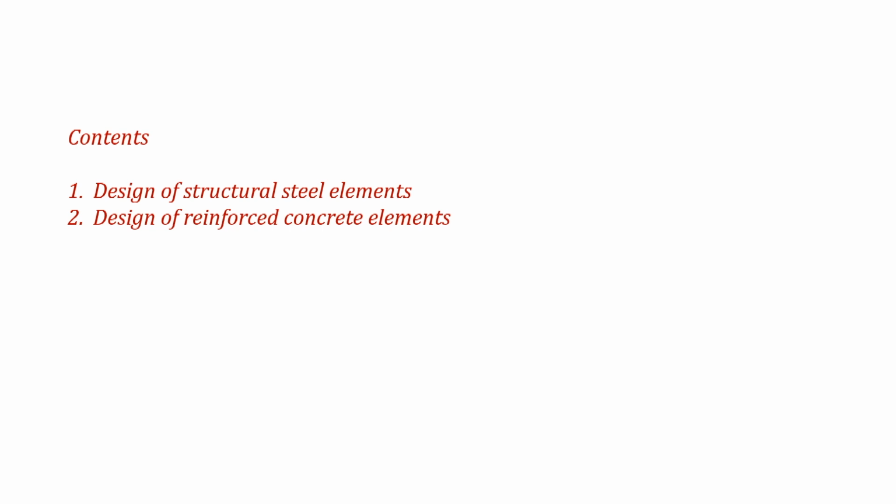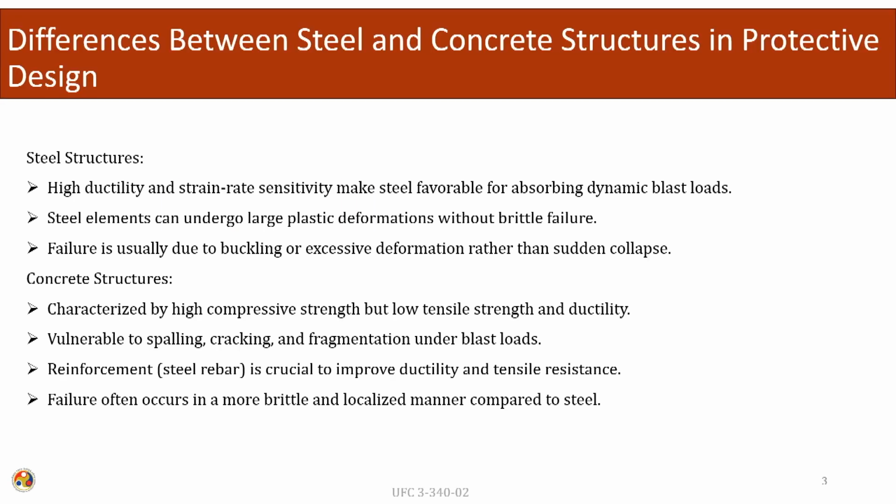to blast loading. So, what is the difference between steel and concrete structures when it comes down to protective design? Protective design means that we are designing the structure to withstand impact and blast type of loadings. So, the hallmark of steel structures: steel structures have high ductility, and they have strain rate sensitivity.